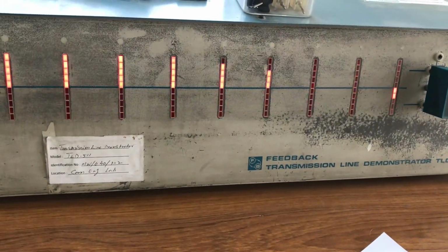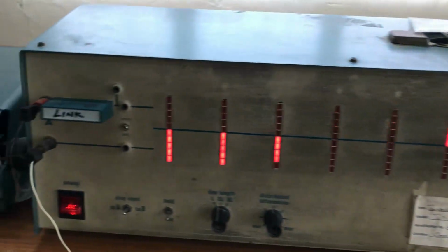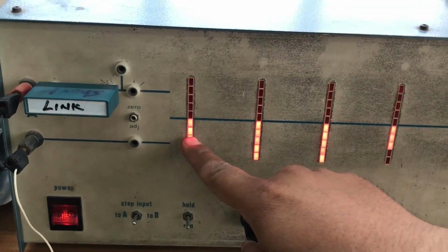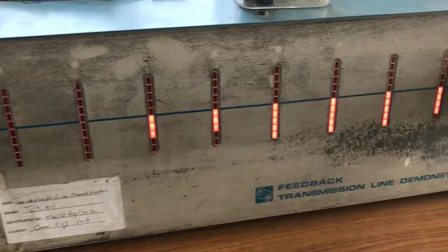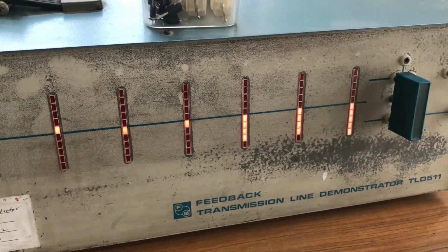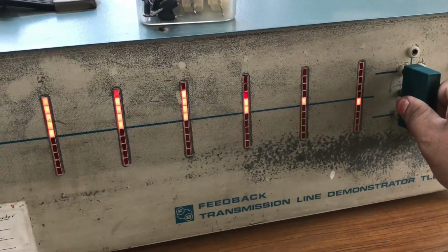In an open circuit, normally I have voltage at the end of the transmission line which is going to be a maximum voltage, whatever is coming from my source to my transmission line. So at the end of my transmission line, if I have an open circuit, I should see a maxima. So let's look at that maxima. All I need to do to make an open circuit is simply take this load off.